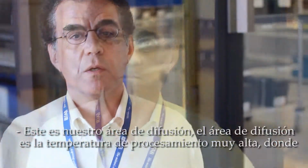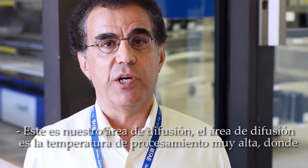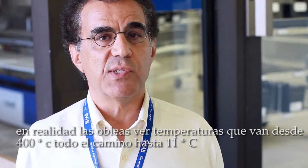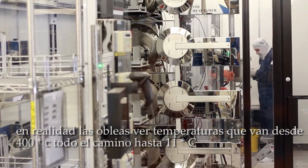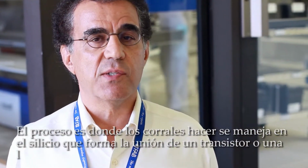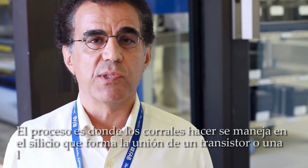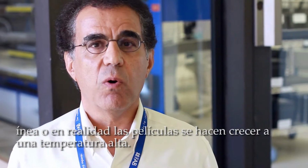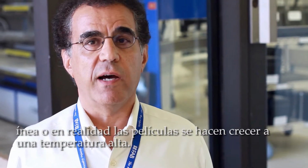Depending on the film chemistry, various gases are introduced in the plasma environment, and the films are etched in that area. Okay, this is our diffusion area. The diffusion area is a very high temperature processing, where the wafers see temperatures ranging from 400 degrees C all the way up to 1100 degrees C. In the process, the dopants are driven into the silicon, forming the junction of a transistor or a diode, or films are grown at the high temperature.